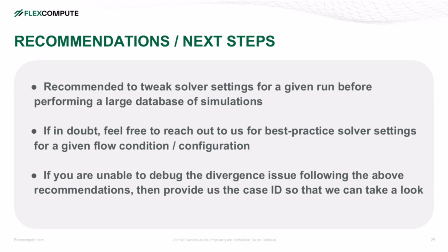Before we wrap up, I will leave you with a few recommendations. For large aero databases, a practical approach is to first run a subset of representative cases to determine good solver settings. For these test cases, you can experiment with more aggressive convergence limiting factors and pseudo-step counts, monitor residuals and forces, and then apply the tuned settings across the broader database.